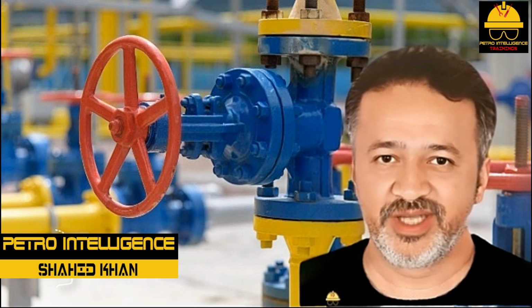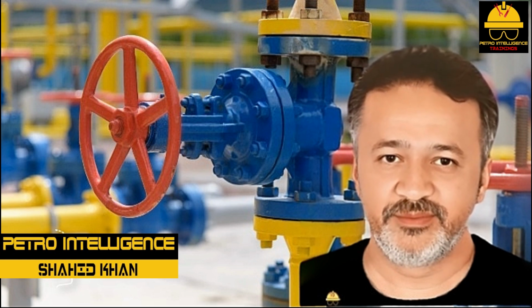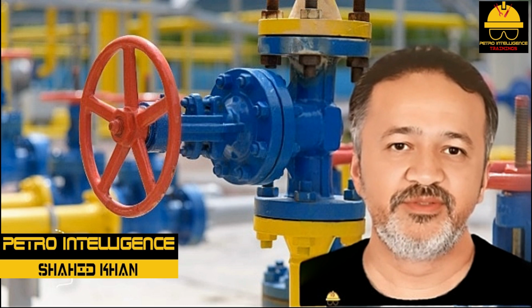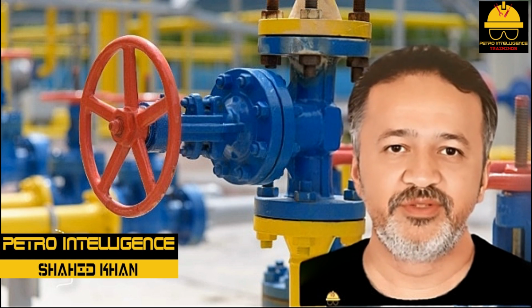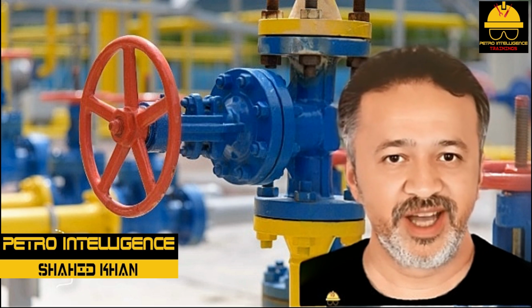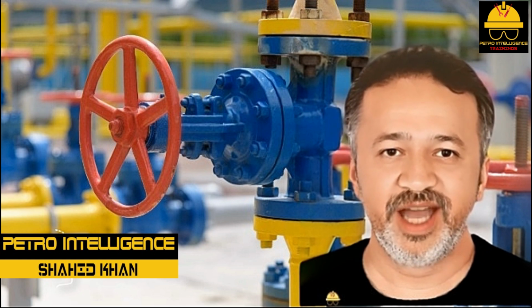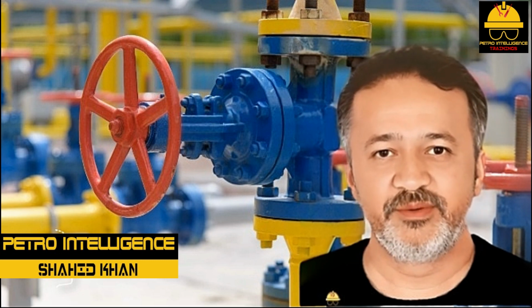A process technician can look at this type of valve and tell if it is open or closed by checking the position of the stem. Another type of rising stem valve is threaded at the bottom of the stem. In this type of valve, the handwheel is firmly attached to the stem and rises with it as the valve is opened. A non-rising stem gate has a collar that keeps the stem from moving up or down.